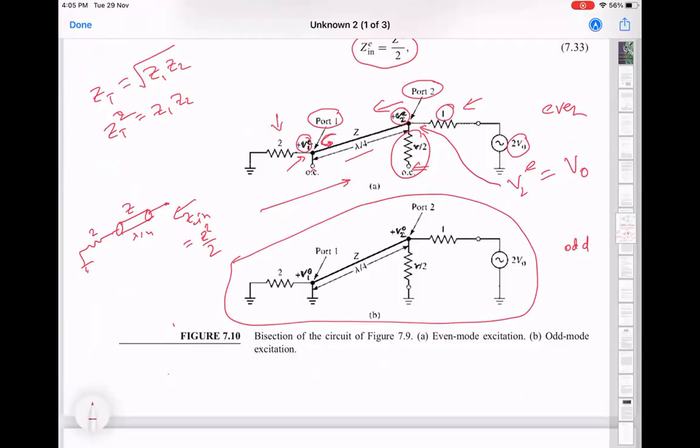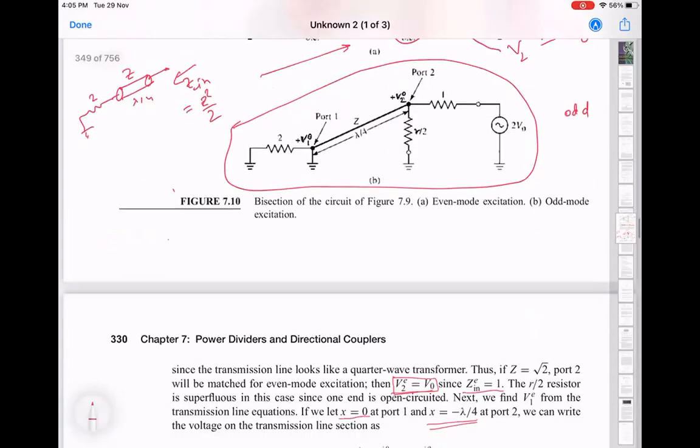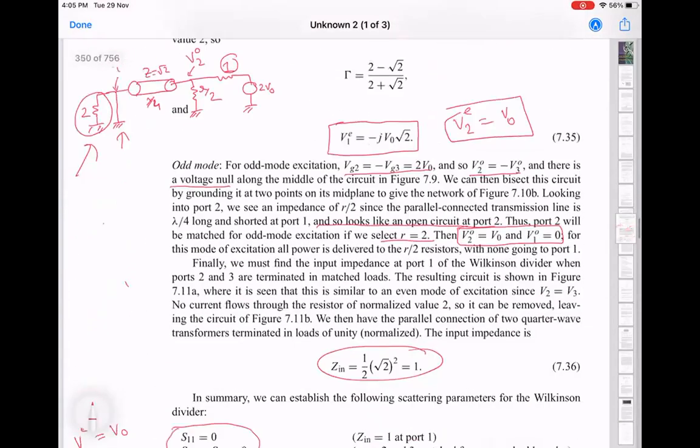So there is no power flow going across from one to the other. And for the odd mode also, it's not going because there is a connection to ground. So both the fact that you can either have an open circuit or short to ground isolates these two circuits completely. So nothing you send on port 2 will arrive at port 3 and vice versa because of symmetry.